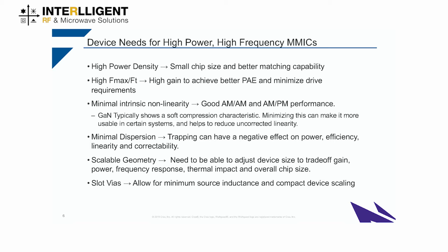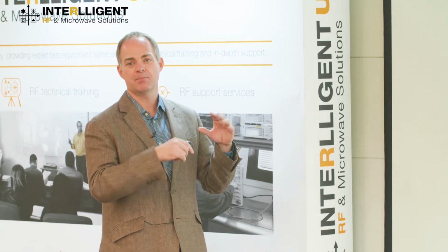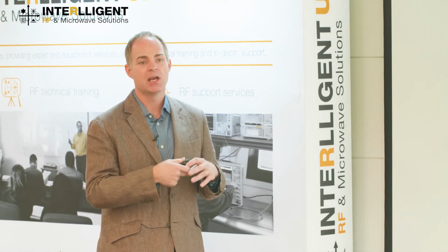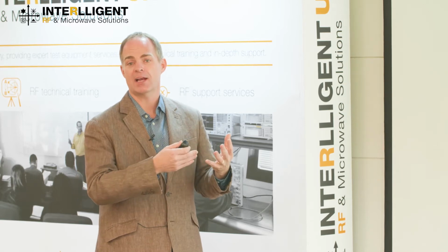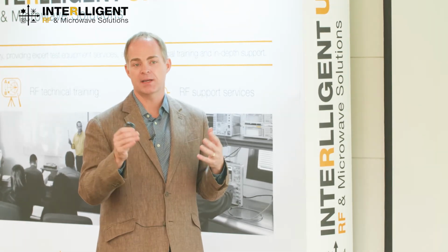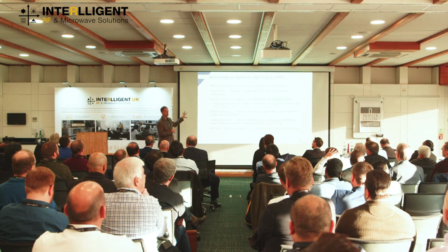Now, traditionally, gallium nitride has had, I won't say issues, but has had the characteristic of having a very soft compression. So in order to get peak PAE, you typically have to drive these things 4 dB or so into compression for the output stage. We've taken that into account in our 0.15 micron process. So what we've seen is that we're actually able to achieve P1 dB efficiencies and powers that are within a half dB of our PSAT efficiencies through some engineering and some design in the bias circuitry. And I'm going to show a little bit about that on one of the MMICs that I'm going to discuss later.